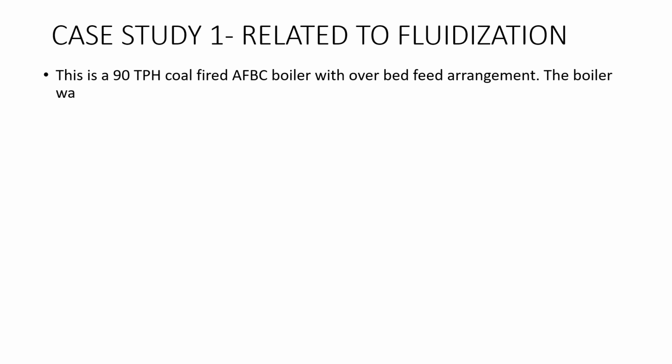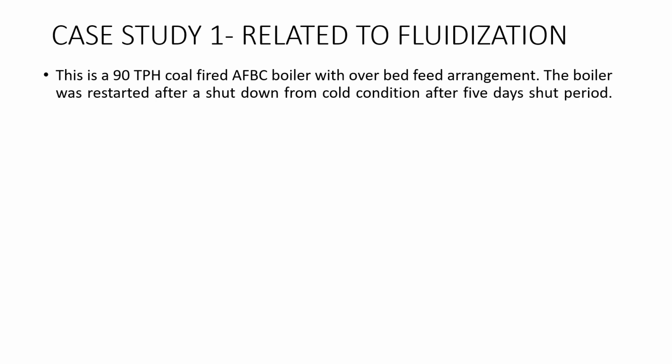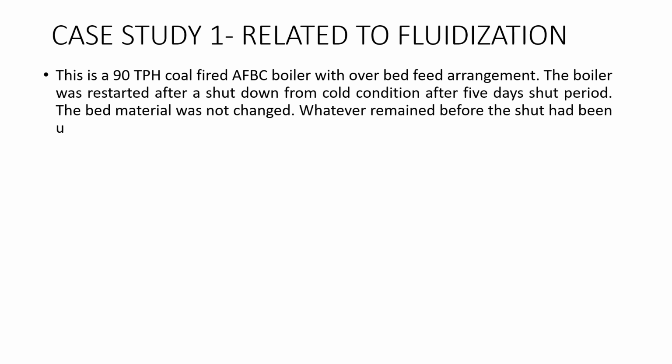Now we go to the case studies related to fluidization. Now this was a 90 TPH coal-fired AFBC boiler with overbed feeding arrangement. The boiler was restarted after a shutdown from cold condition after a 5 day shutdown period. The bed material was not changed. Whatever remained before the shutdown has been used as such.